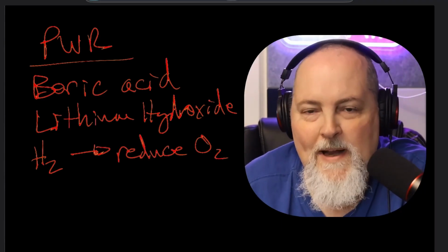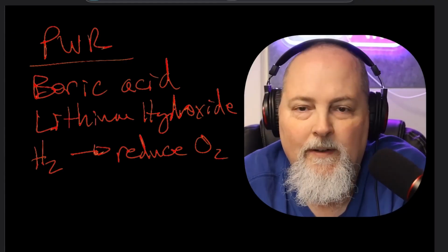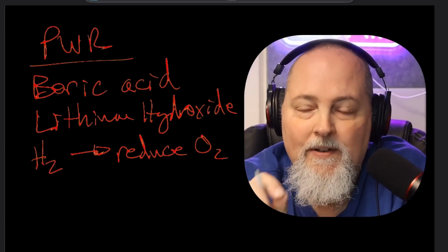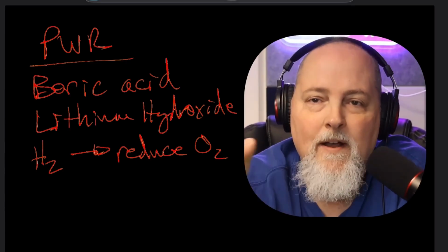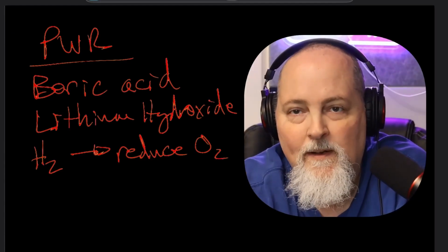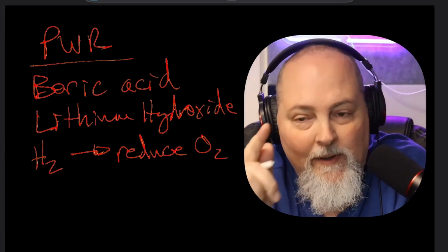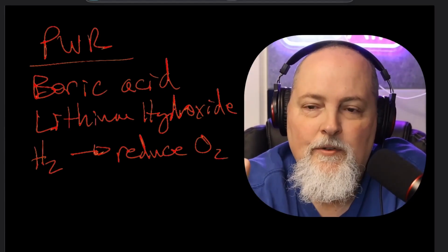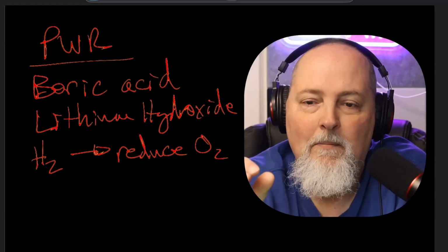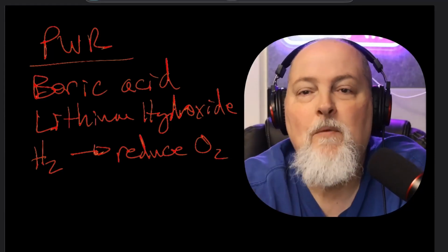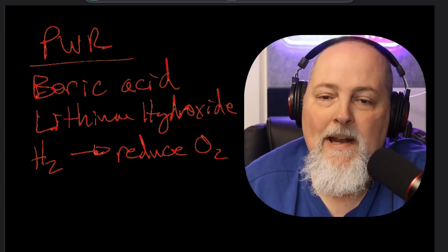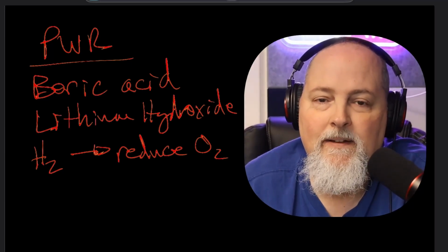So what happens when air gets in? Air brings in oxygen and nitrogen, right? The major reaction is between the oxygen and the dissolved hydrogen. If we add enough hydrogen, and there's been some radiolytic decomposition and the oxygen has built up, then the oxygen is consumed and the system stays copacetic, right? But if enough air gets in, then we can deplete that hydrogen inventory, that excess hydrogen that we've been adding, and then the chemistry shifts.